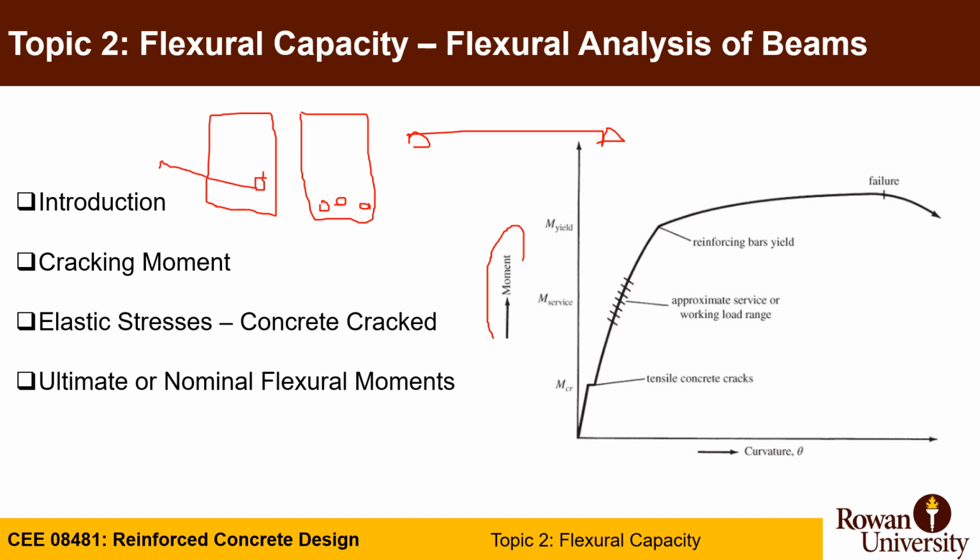At the fiber level, this fiber is made of material, either reinforcing steel or concrete, and we will be interested to know what is the stress strain curve of this material. So this applies to a single fiber. A group of fibers, as I mentioned, creates a section, and for the section we will be interested to know the moment curvature.